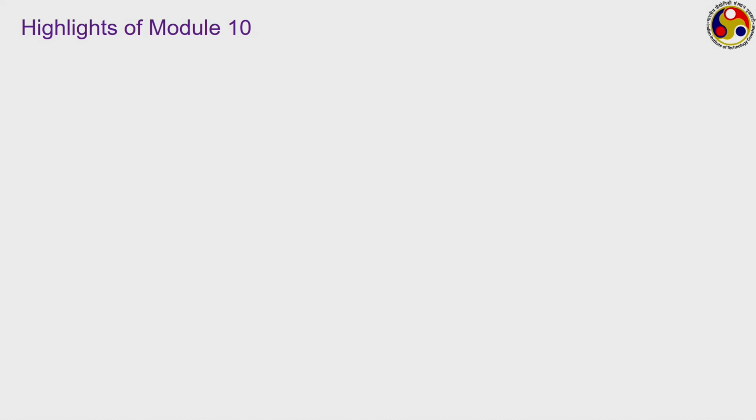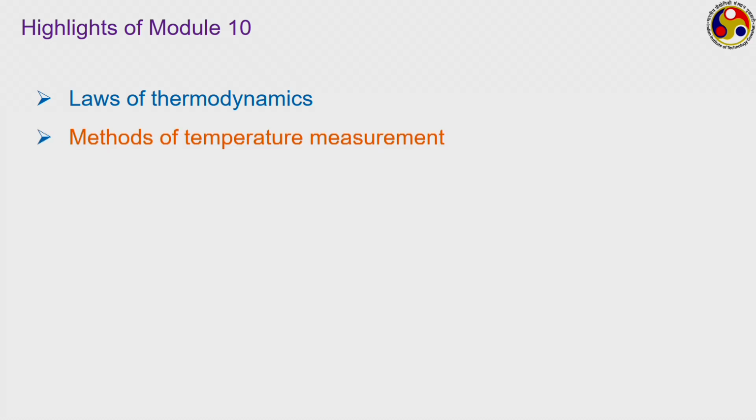So, that takes us to the end of this module, where we have talked about the measurement of temperature following different principles. We started with the laws of thermodynamics, particularly the 0th and 2nd law, to define the thermodynamic temperature scale. Then we categorized the temperature measuring options into 5 different categories, out of which we discussed the expansion based devices in the form of liquid in glass thermometer and bimetallic strips.